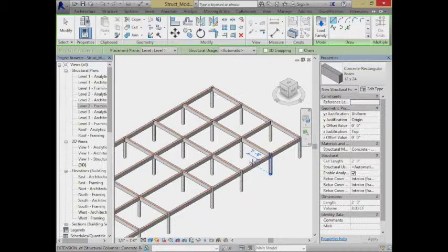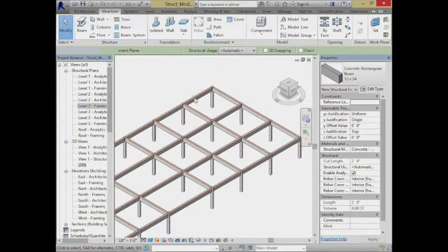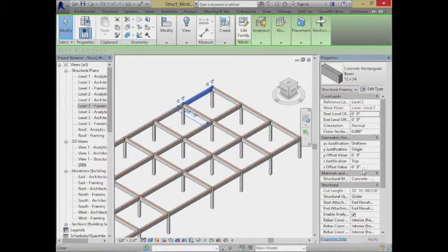When you're working with steel, though, you have to be a little bit more cautious. With steel, you often have some deck, some sort of metal deck underneath it. So it's concrete with a metal deck underneath. When you go through and put the steel beams in, you don't actually want to have them protruding up into the column or into the slab. You want them sitting underneath the slab. So if you're putting steel beams in, you just have to remember to give them a little bit of an offset down. How that looks is, for example, here's a beam, there's a Z offset.